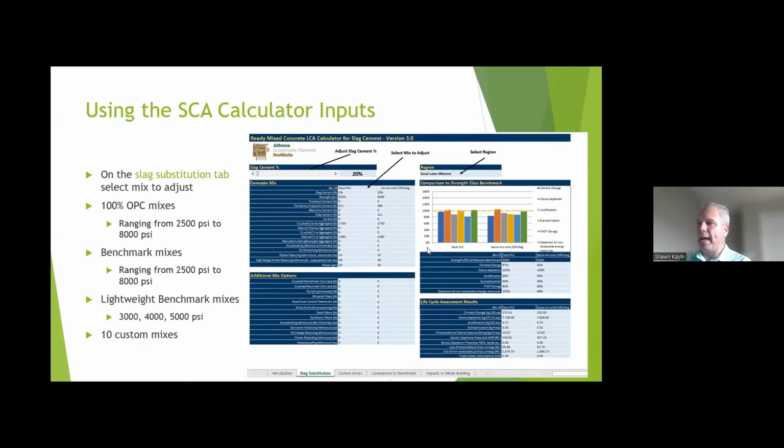We can now take that and look at it and compare it when we add in more slag or less slag to see what we need. And a lot of these cases where this can help us out is especially now, such as the GSA and the new BABA laws that have come in, which are now requiring low carbon cement and low carbon concretes to be used. And in those cases, the GSA has now created a sheet or a template that says, if you're using a 3,000 PSI mix, we want you to have a global warming number of this or less.